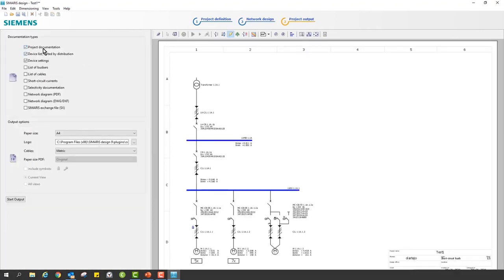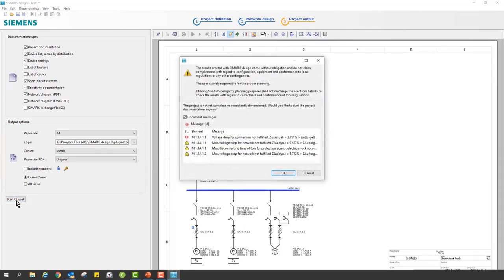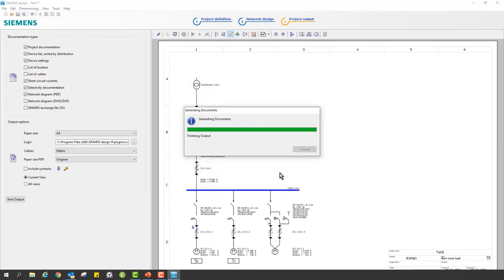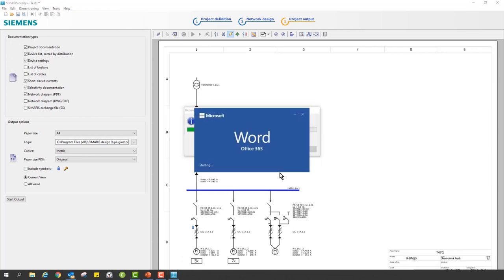I get some data out of it, and then if I come again to a protection device that I wanted, you will see that now, since this one is not so big, I'm becoming a backup protection, but I am not being selectable here because it is almost the same and the same graphs. You see, it's almost the same. So actually, here I do not know which breaker will trip, either in overload or in short circuit current. Just take this into account.